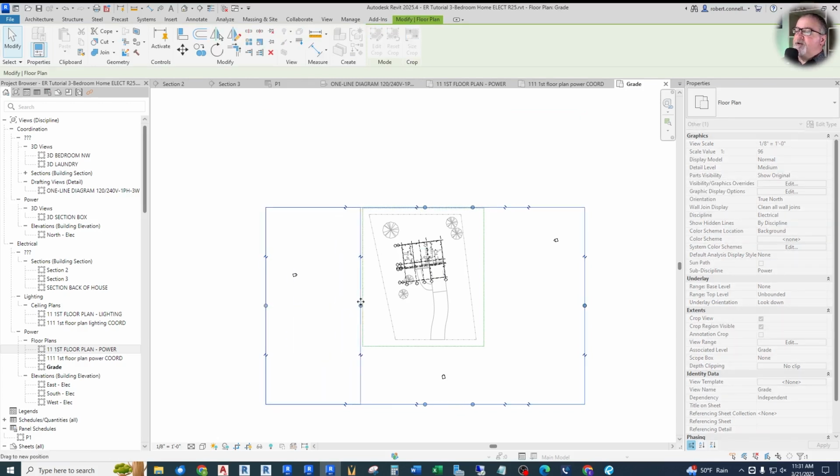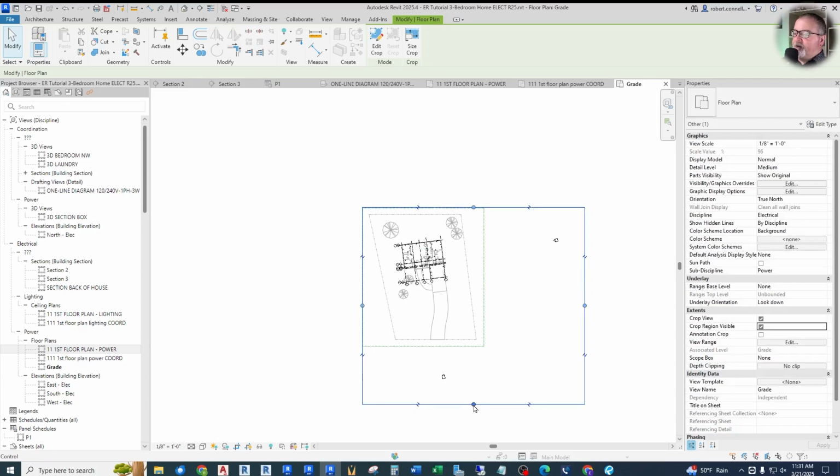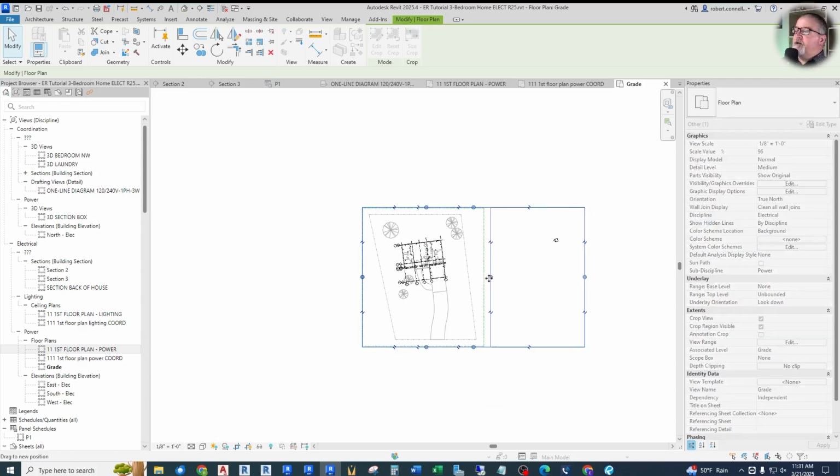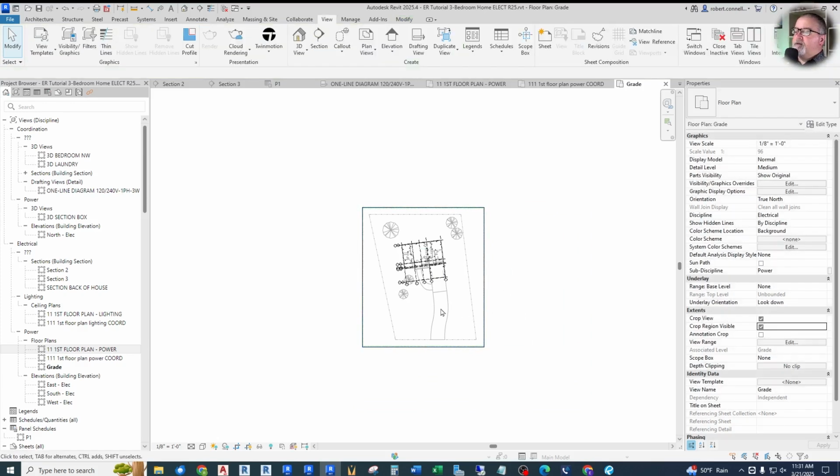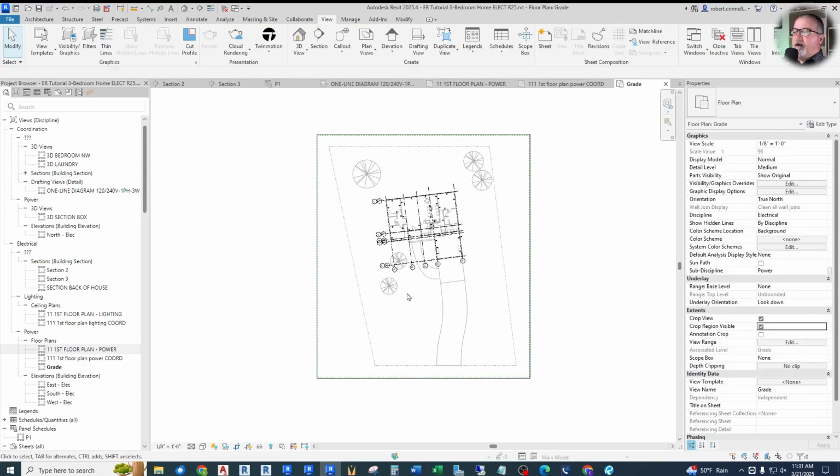I can't use the scope boxes in the architectural. I would have to create my own if I wanted one. But I can use it to help me pull in the crop. Something like that. Now, what scale do I want my site plan? Well, I would typically base it upon the same scale that either my architect did, or if you have a civil engineer doing site work on this job, kind of mimic what they've done. And they are typically not in 1/8 inch or 1/4 inch. They're more of a 1/10 of an inch, 20th of an inch kind of scale.